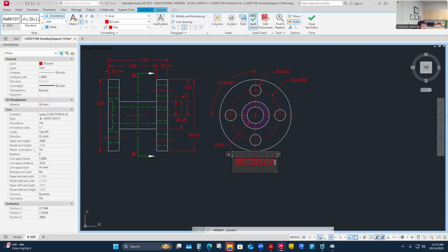And if I do that, I need to tell the viewer that this is at a different scale. I'd probably write the word scale and then write the ratio of the scale there. I could also write the material, or quantity, or a little local note even underneath it. But I would say mostly it carries the scale. And if it's been revolved or rotated by some degrees or anything like that, I'm going to put those details in a note.